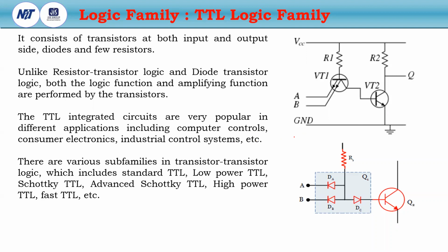Most of the 7400 series ICs are manufactured in this type of logic family. There are various sub-families also, which I already discussed in the previous lecture: standard TTL, low power TTL, Schottky TTL, advanced Schottky TTL, high power TTL, fast TTL, very fast TTL, etc.